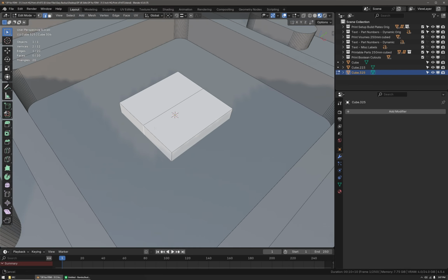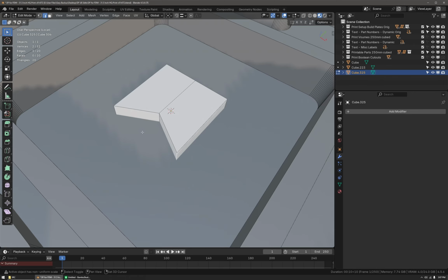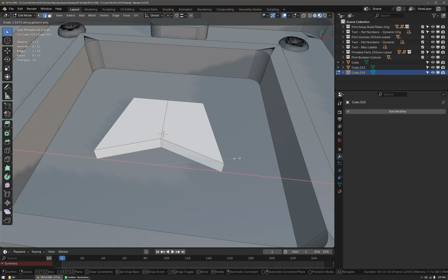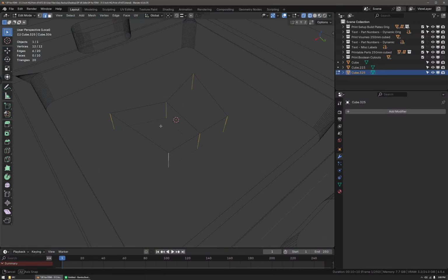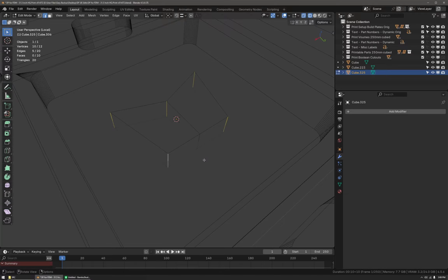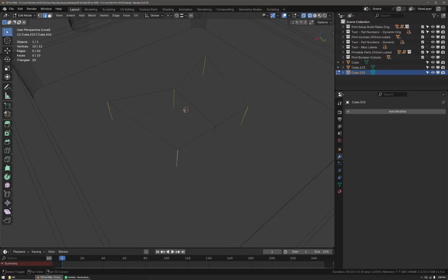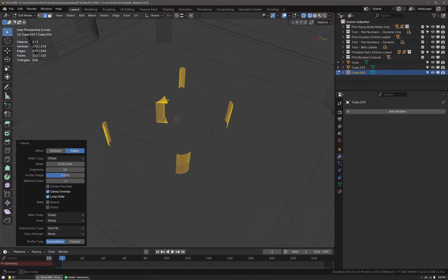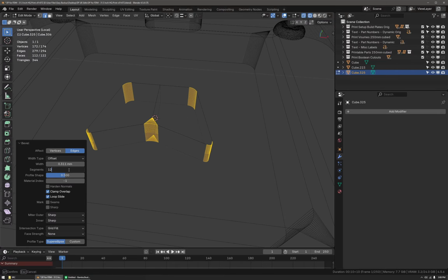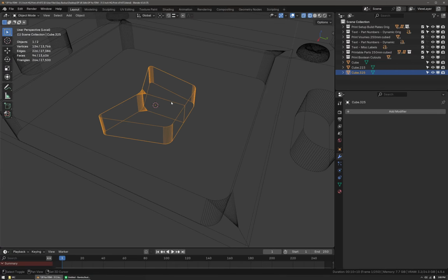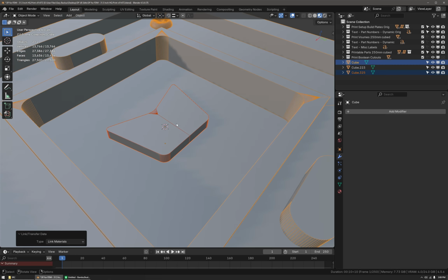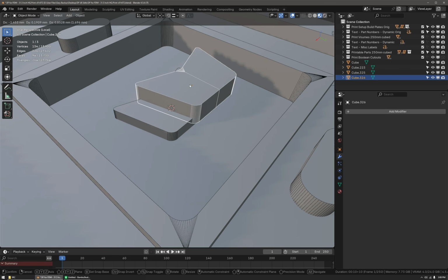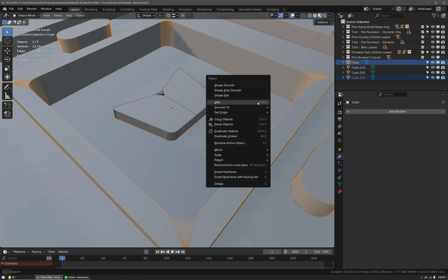I'm going to add an edge loop, and I'm just going to move this like this, select these two, and do that. And now I'm going to go into here and Control Alt, select that edge ring. We're going to deselect that one, and now press Control B to bevel. And 12 segments or even 8 is more than acceptable here. And now I'm going to inherit the material here with link materials, Shift D to duplicate that, select this object, right click join or Control J.